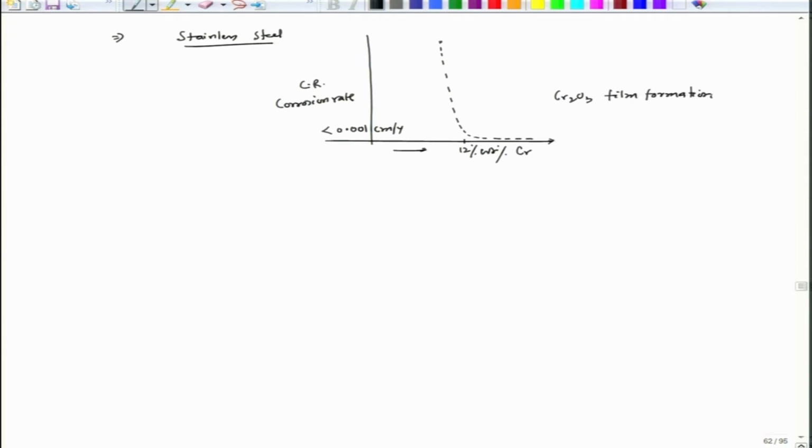In case of aluminum, it is Al2O3 that forms and passivates aluminum. Now, interestingly, aluminum is also a metal used as a sacrificial anode. As we noticed when we talked about sacrificial anode, the anode material should dissolve spontaneously, so that it provides the required electrons for the cathodic reaction on the cathodic surface, which is the iron, and that is how the iron is protected from corrosion.